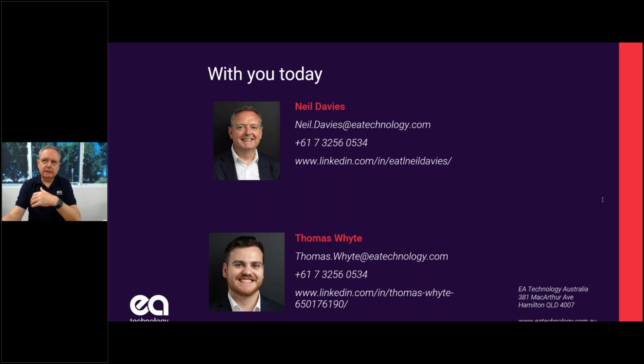So offline testing has its part. Offline testing can be very much more sensitive to finding very small levels, but often the case is you're finding small levels of discharge in offline testing which are not particularly going to cause you immediate problems. So the application of non-intrusive technology is very much easier to deploy. You can test a lot more assets a lot quicker, and you can find the things that are likely to cause you a problem in the short term. So they both play their part.